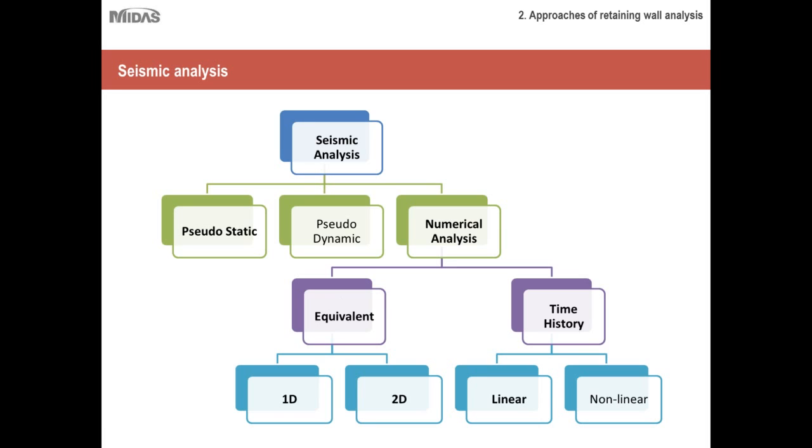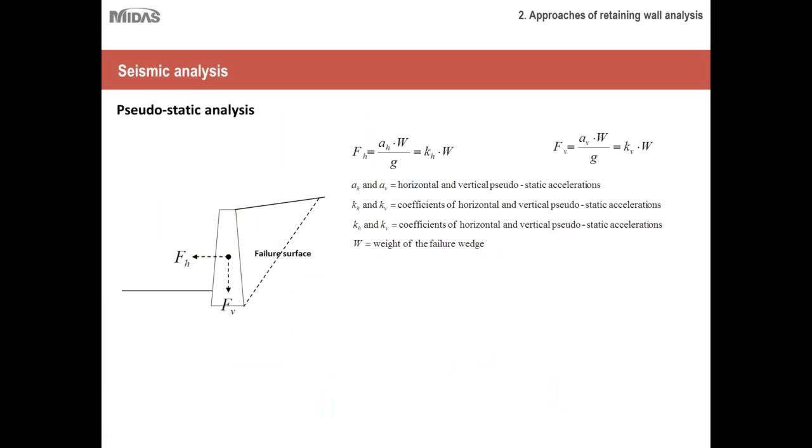Now the reason I've done this is that pseudodynamic and nonlinear time history analysis are rarely used. I haven't seen any engineer applying pseudodynamic analysis. I have seen cases where nonlinear time history analysis is needed in very high seismic zones, but pseudodynamic analysis is hardly used. So let's go into a little more detail about what these methods are and their formulation.